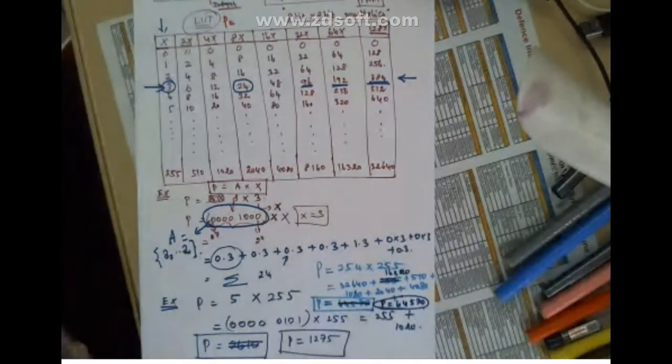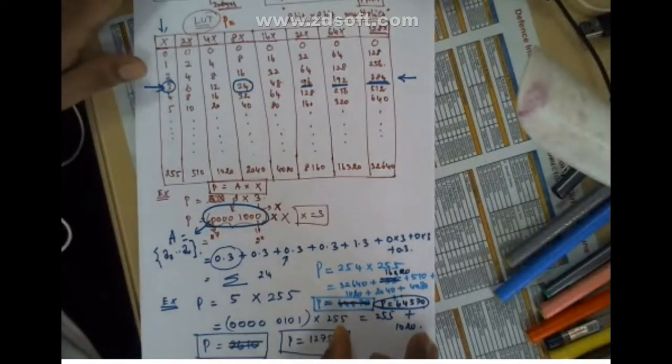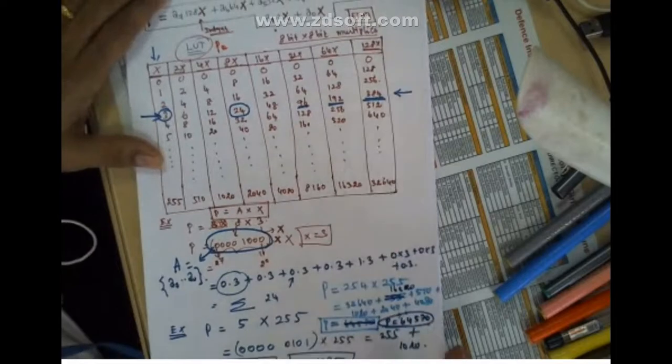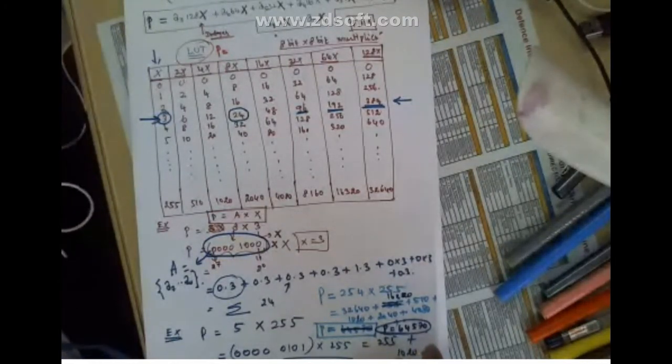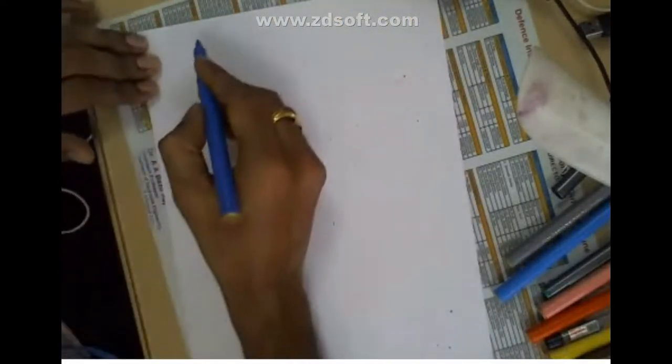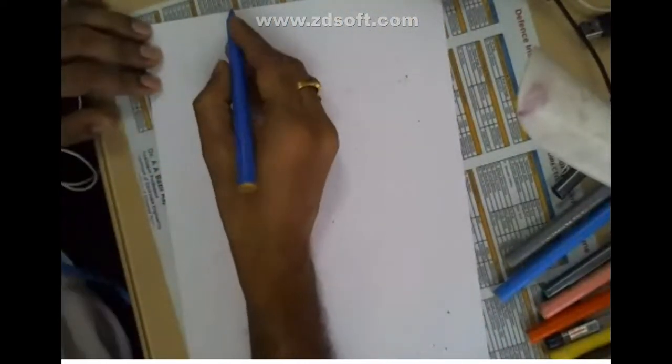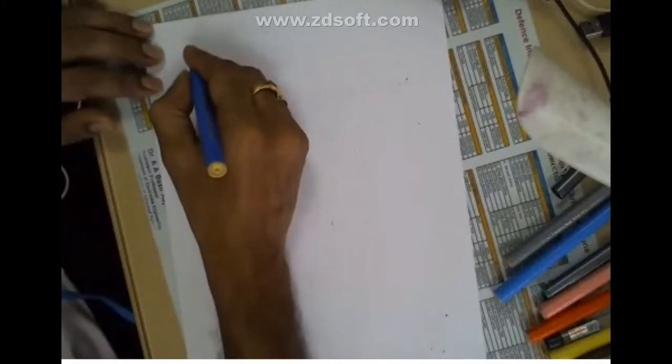Fine. So now we came to know that a lookup table creation and then selecting the appropriate elements in the table based on the binary value of A will solve the multiplication of 8 bits. Now, how do you implement this with the pipeline architecture in the FPGA? So I am drawing the structure something like this. You take this structure.